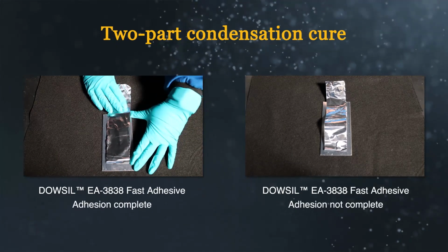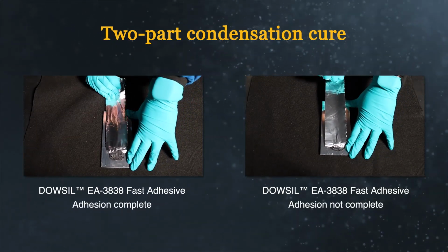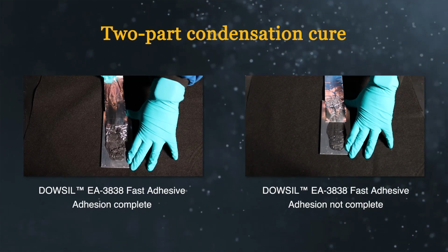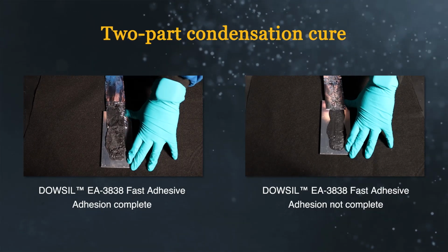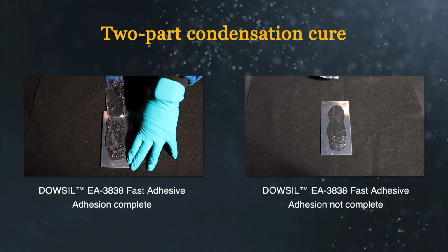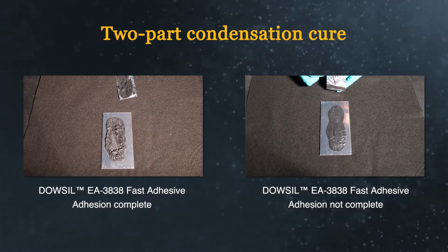While many tin cure products cure within minutes, those with built-in adhesion, called self-priming, require more time for adhesion. Newer adhesives achieve strong adhesion in 24 hours, while others require 3 or more days for adhesion to build. Tin cure products can obtain their other properties well before adhesion.